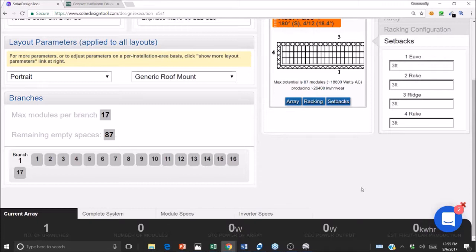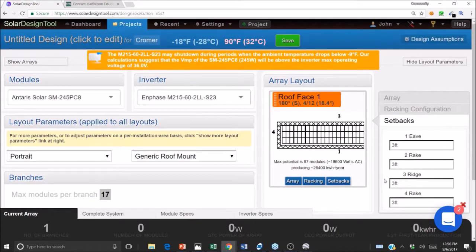That applies when there is no forced air ventilation system to ventilate smoke out of the attic during a fire. Without one, you need rooftop clearances for fireman access. That's not part of the National Electric Code, but it's still part of code. There's the National Fire Code, of which the Electric Code is just a subset.